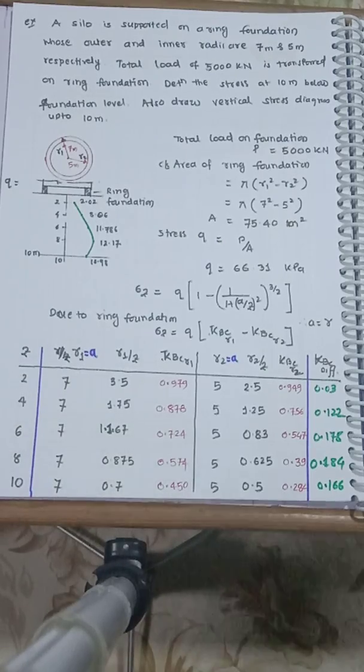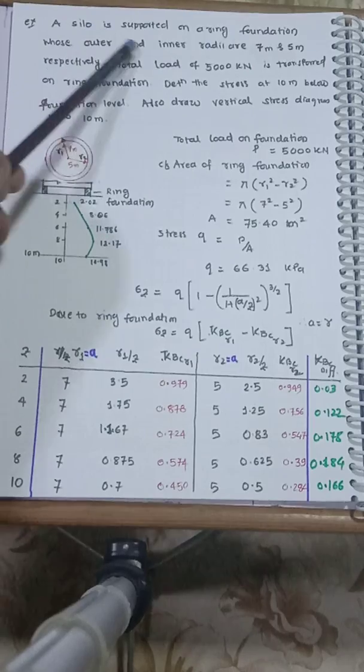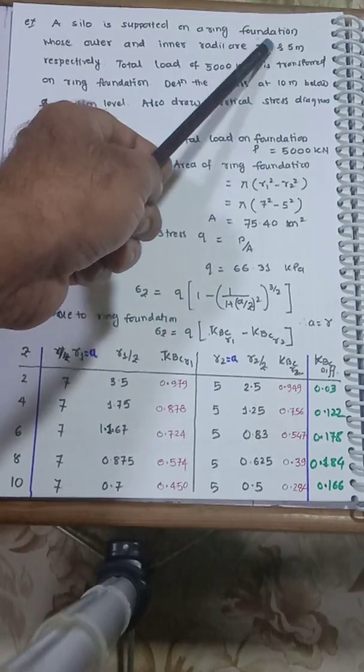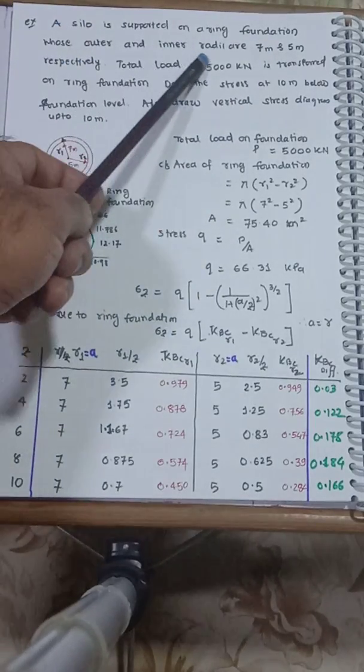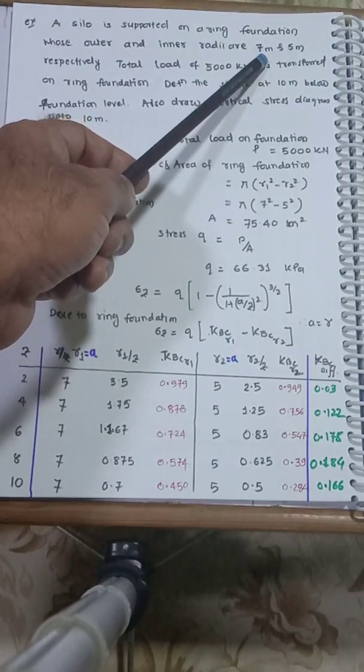It is resting, and even tanks also, on a beam. They call it the ring beam. The foundation is called the ring beam foundation, that is the RCC beam, nearly at the edge, so the entire tank is resting on that. The middle portion is not directly touching, but is filled with a granular material. So a silo is supported on a ring foundation whose outer and inner radii are 7 and 5